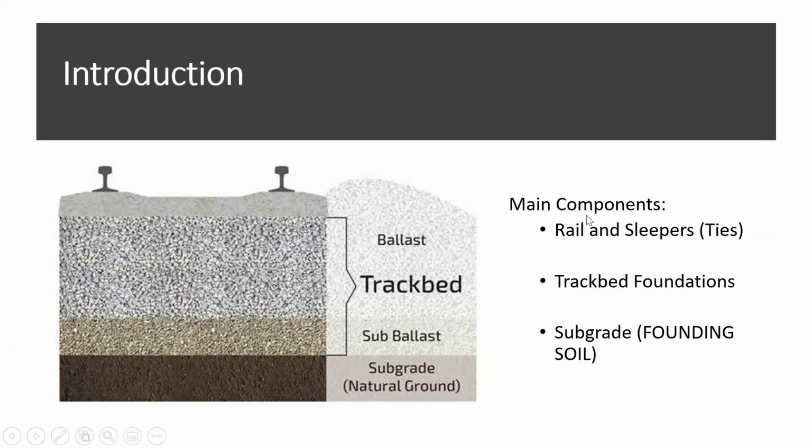So the main components we have are the rail and sleepers, and the track bed foundations, and this is where your input would be required from a geotechnical point of view. And then your subgrade is basically your founding soil.